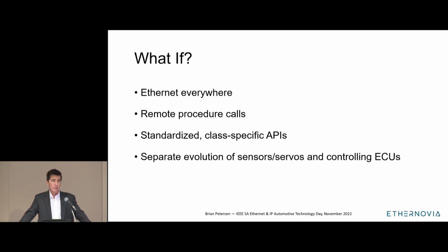One suggestion might be, and this is not my area of expertise, but that never slows me down, to put more intelligence in that sensor. It can go from reporting each tick to, once the ticks exceed a certain number per second, reporting that it's now seeing ticks at this frequency. So you start reporting frequencies instead, and the rate at which you're reporting data caps out, because you don't need to know 10,000 times a second how fast the wheel is turning. You only need to know maybe 100 times a second. So that would be one alternative: just put a little more intelligence out at the edge.